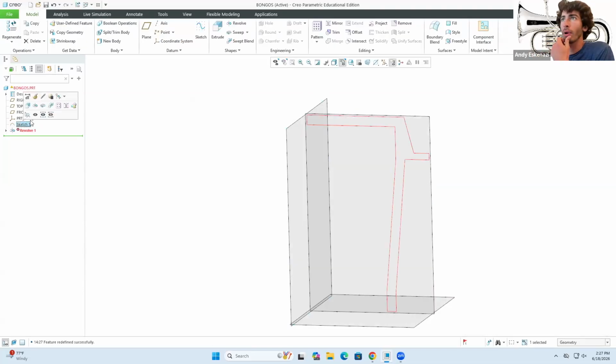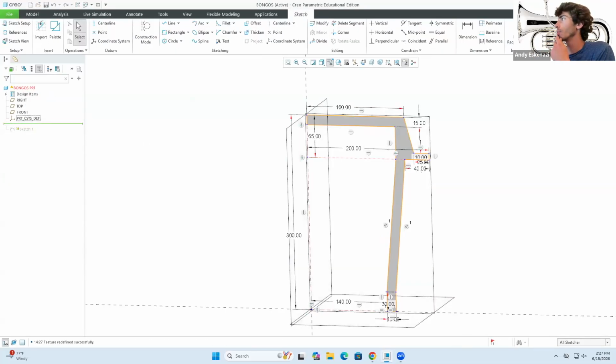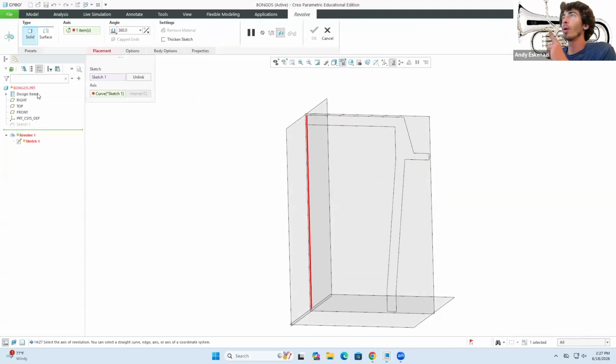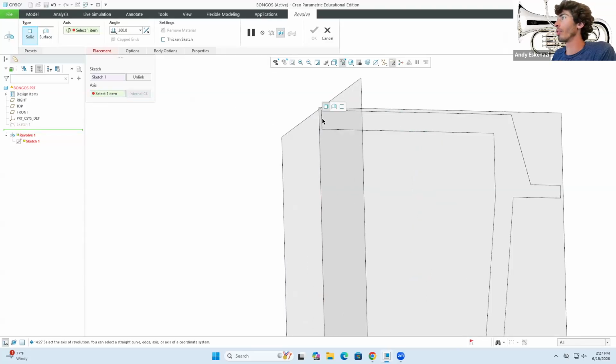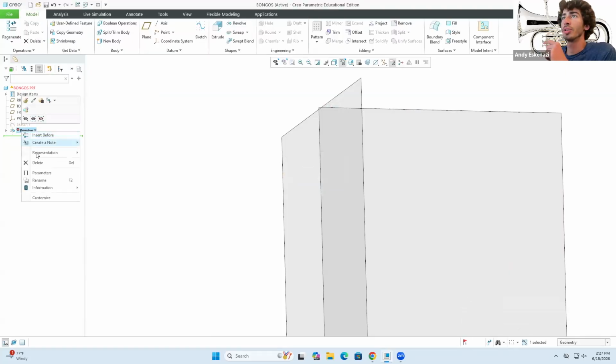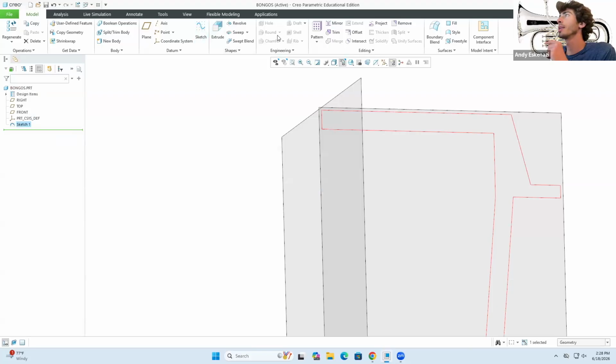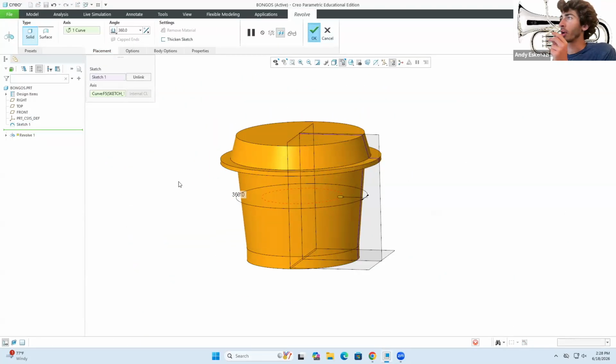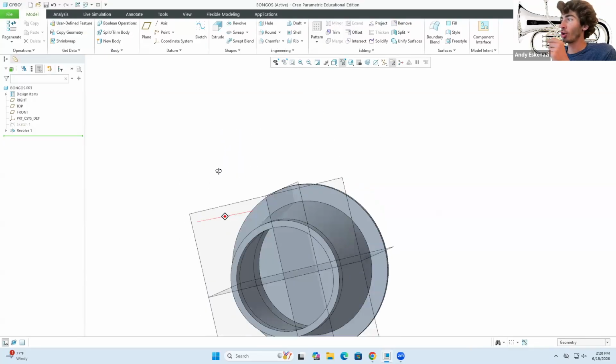Now, obviously, this is not going to work because I need to. Oh, there we go. Sorry. Yes. Because I'm going to edit my axis of symmetry. So instead, I'm going to use that line. Answer yes. Let me just delete this for a minute. Let me show this again. Let's do a revolve along here. There we go. Okay. So now you see how it's hollow.